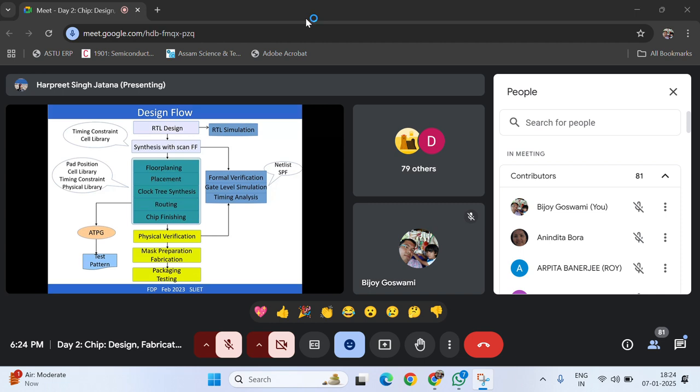Then the clock tree. Because in a synchronous design, there is a single clock which is coming, either being generated inside the chip by PLL or DLL. If the circuit is supposed to work at say 400 megahertz at 130 nanometer or 180 nanometer, it's very difficult to give a clock through the pads, because pads have big diodes for latch up protection and ESD protection, particularly ESD protection.